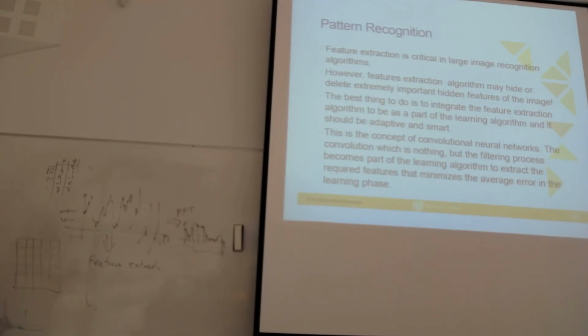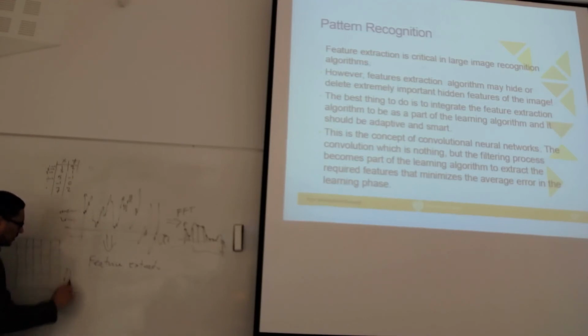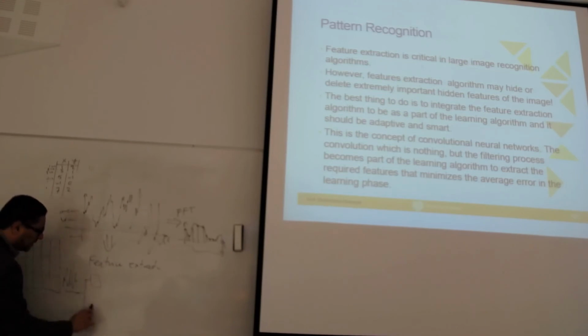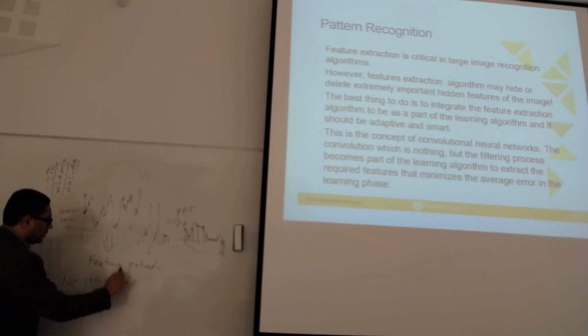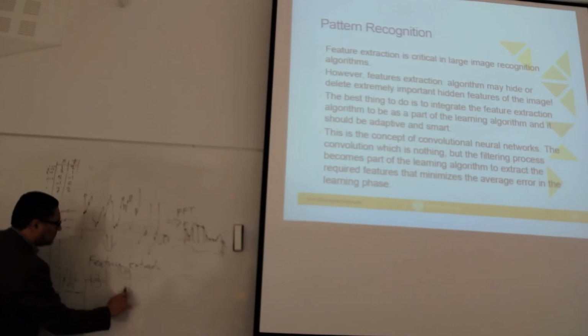If you want to build a system to recognize the voice of people, then one possible way is to use filter banks. So this is the voice signal. Then we might have a low pass filter and a high pass filter, and then again low pass and high pass. So every subband is divided into low pass and high pass, and so on.